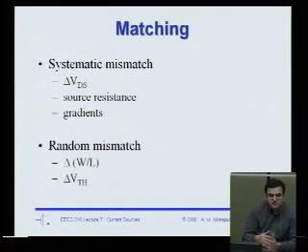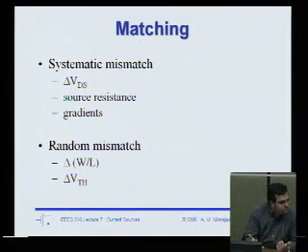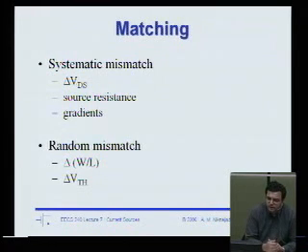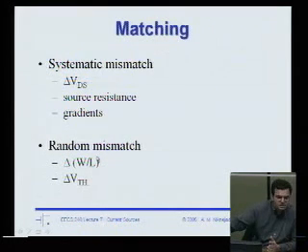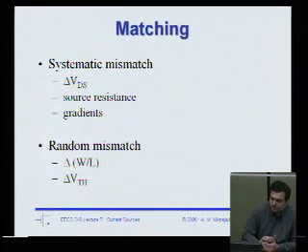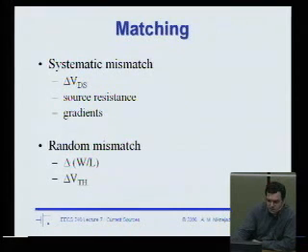And you might argue that C-ox is going to vary, right? The thickness of the oxide is very thin, so that should vary. Mobility should vary, because mobility is also a function of doping. But for simplicity, we're going to lump all the mismatches into this term. The reason we can do that is because they're all multiplied together, right? You have mu C-ox W over L. So let's just lump it and call this mismatch delta W over L. So it's an effective W over L mismatch that compensates for C-ox and mu.